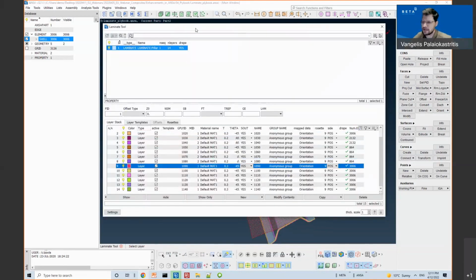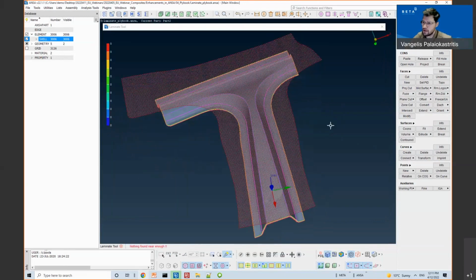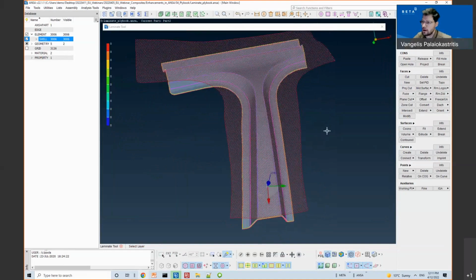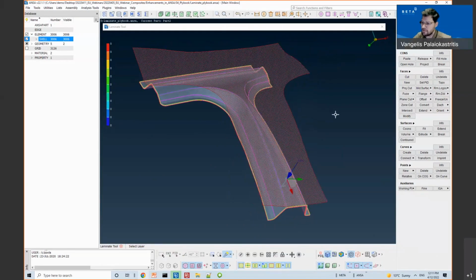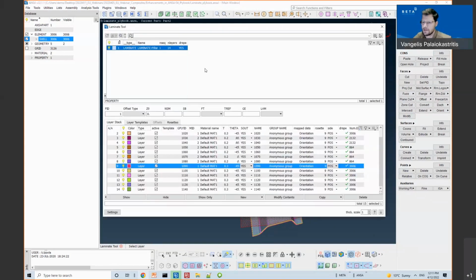So the flat pattern is actually the opposite result of the drape. If this is the initial pattern of the layer, and if it is draped starting from this point, which is the rosette, and around this geometry, I will get the result that the drape has calculated.